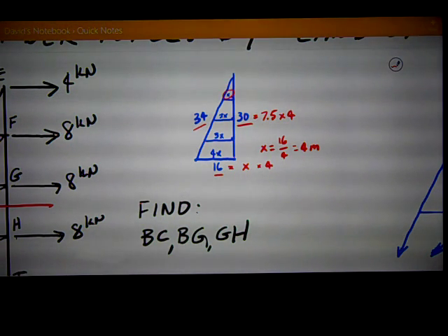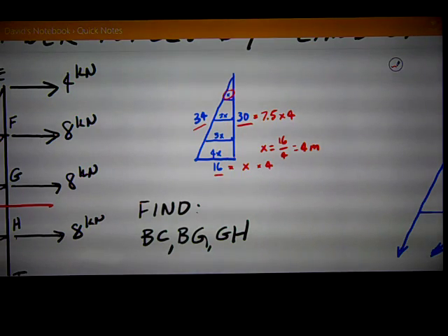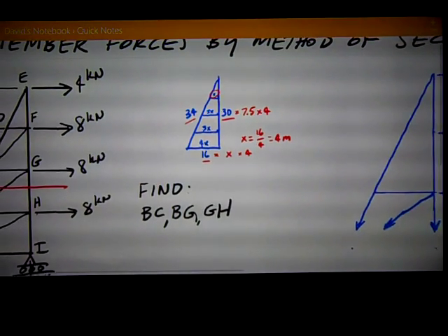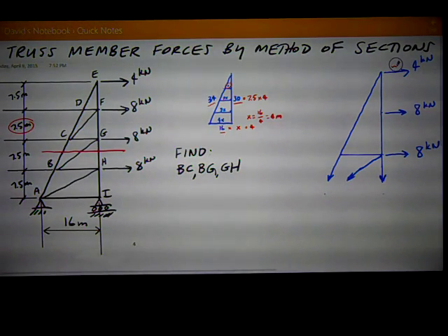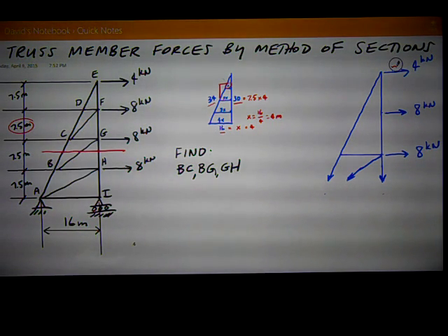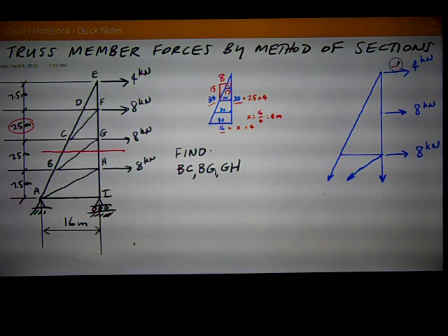So at the top we have this x, which is 4 meters, 2x, 8 meters, 3x, 12 meters, and 4x, 16 meters at the bottom. So that's sort of the xy, the Cartesian components of that truss. And so we can observe that this outside line is really a 30 to 16 to 34 slope, or really dividing everything by 2, we get 8, 15, 17 for that outside line, which ED all the way down to AB, including CB, are that slope relationship, 8, 15, 17.